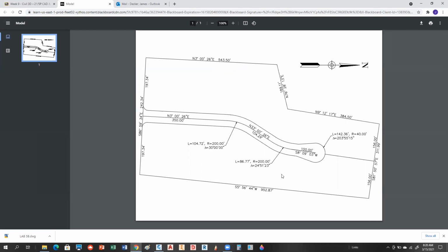But they're really cool when you're doing lot development, say for a subdivision or a big industrial complex where you're busting it up into parcels. We basically had that on the first drawing we did in Civil 3D. We could have done that with parcels. I wanted you to get fluent with line work first because a parcel object in Civil 3D is, like I said, a trickier kind of guy, but you can think of it more or less like a closed polyline.